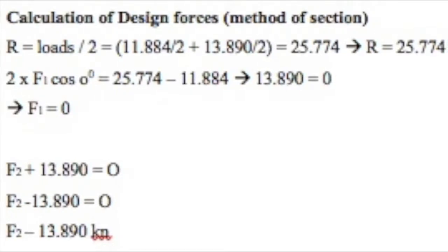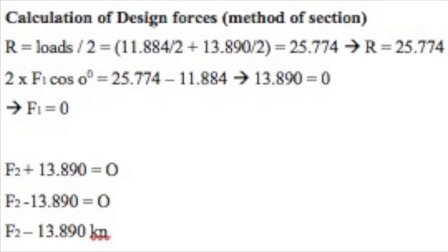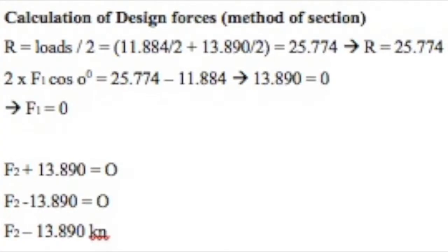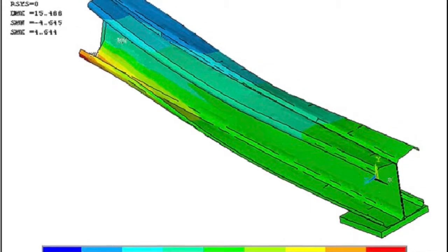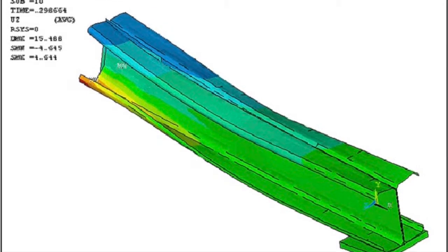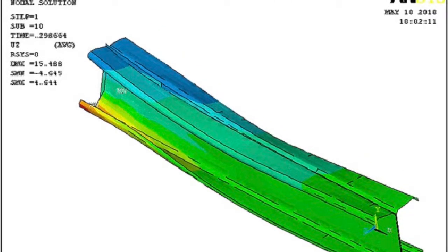The final part of designing the member was to determine the elongation of the member, where we assumed that the rectangular hollow section would be chosen. Now that the roof bracing system had been completed, the wall bracing system could then be calculated. The first step was to determine the RB value.